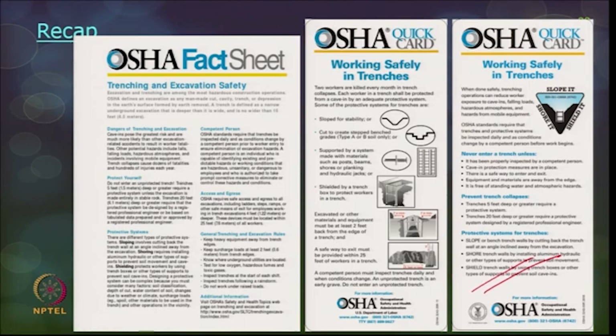Based on the type of soil, you may have to choose your slope angles or bench angles, and when you are going for benching, you can do it only in type A and B soil; you cannot think of type C soil. Shoring is primarily a system which comes with timber, aluminum and a lot of hydraulic jacks, and shielding is nothing but a trench box. The trench box picture is shown here.